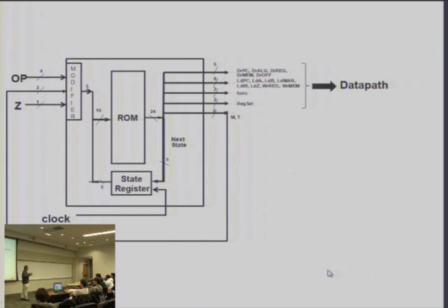I can go through my sequence and see that, oh, when I'm in fetch state, I fetch 1, I need this drive PC to be on, and perhaps in I fetch 2, I want it to be on, and so on. Some BEQ state I want it to be on. So this is basically a logic equation, right? There's a logic equation, and you can implement this using AND-OR logic, right?